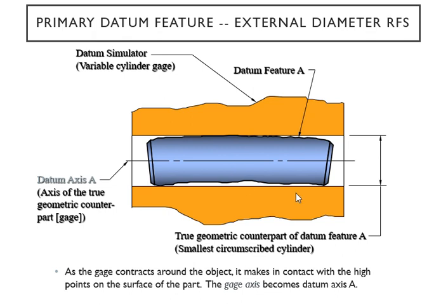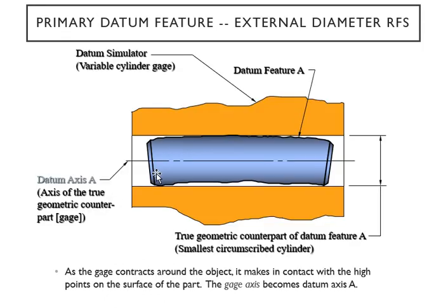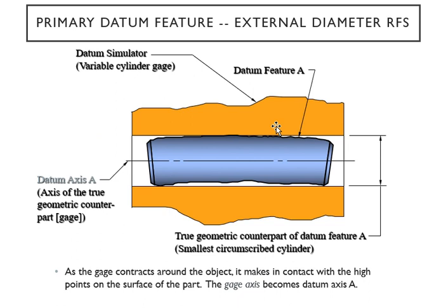When you put it in, since this is so perfect, your cylinder that you saw, what looks perfect, is going to have some imperfection on the surface. Your datum axis is going to be A, which is this guy here, in the two-dimensional perfect picture. This is gauging and measuring that datum feature A right there.